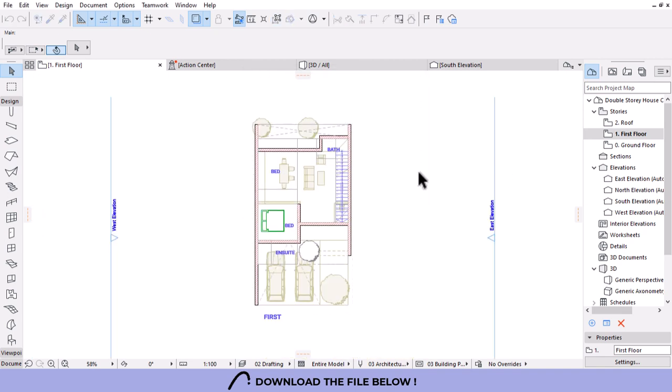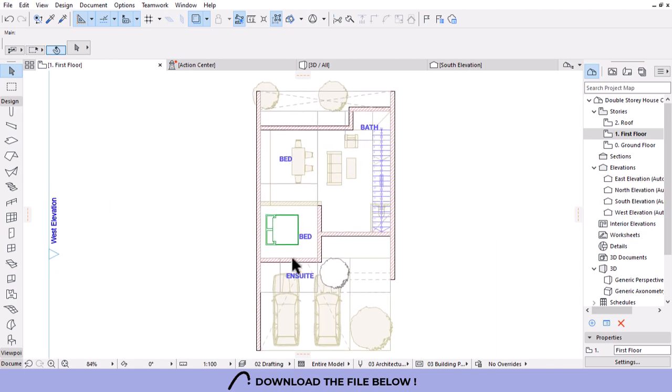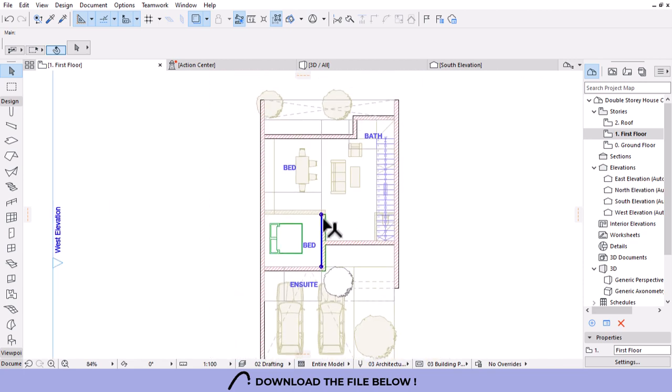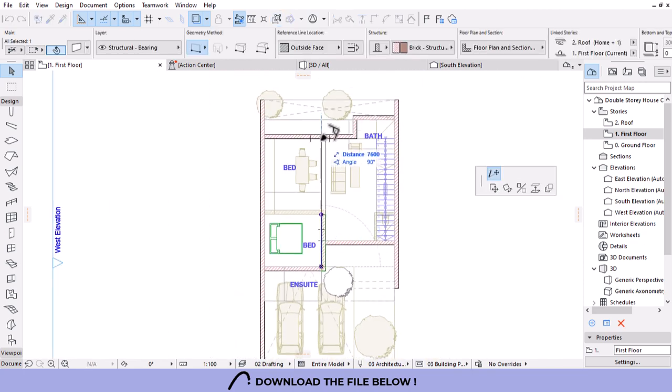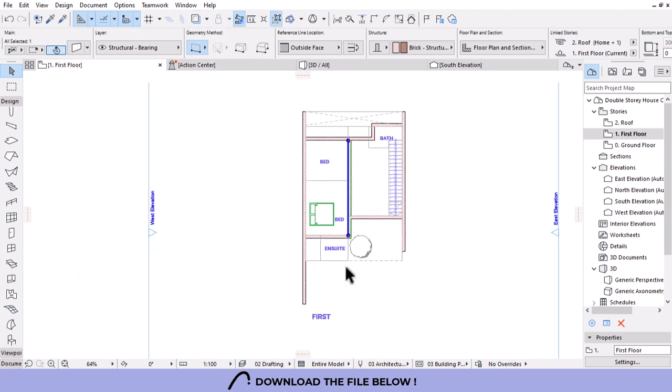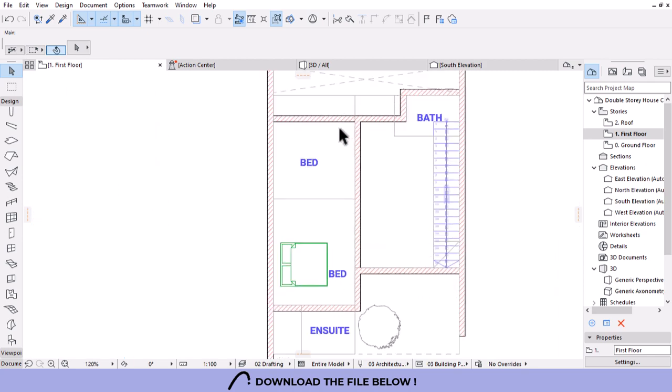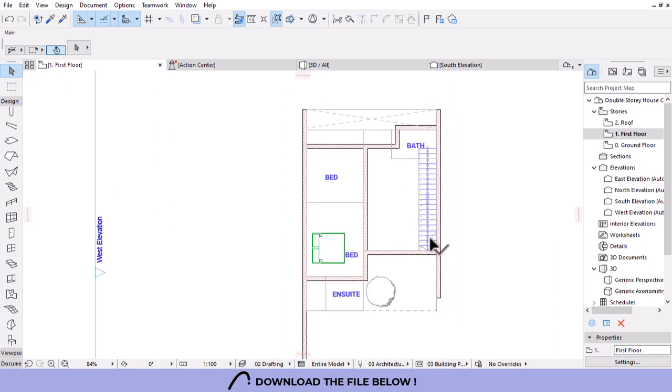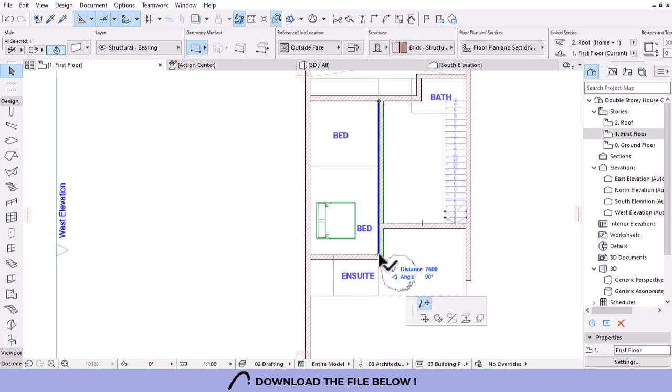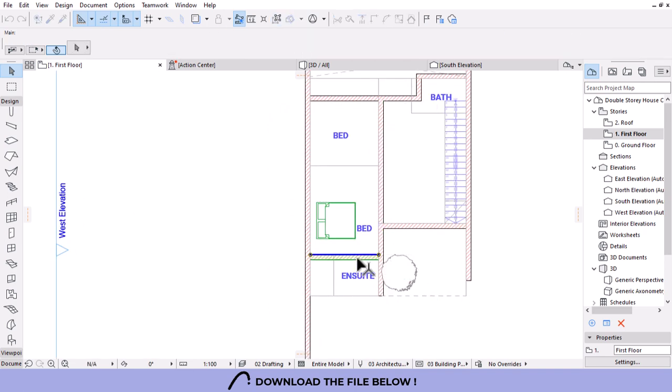That's the way. And then click outside for the paste, and then you can take this wall and stretch it to there, or maybe let's switch off the tray so that we can see we are dealing only with the first floor. There we go. So this is going to be stretched to this corner,